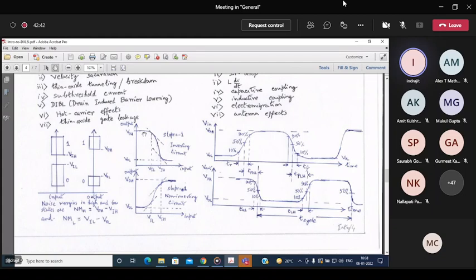Now here, as this goes on like this, at 2 points we have got the slope of -1, and those are very salient voltages. At the lower voltage, we call it VIL. So at this input voltage, dVout/dVin is -1, and at the higher voltage VIH also dVout/dVin equals -1. And similarly here, dVout/dVin equals +1. So we will talk in detail about these voltages.